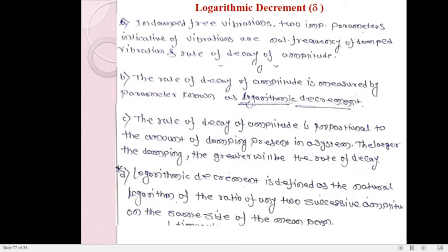In case of an overdamped system, you have seen that the systems do not perform further oscillations or vibrations. As soon as you apply the force, they get displaced from the mean position, reach the extreme position, and from there, depending upon the conditions of damping, overdamped or critically damped, they try to come back to the mean position as soon as possible, but will reach the exact mean position after a certain time, or it will take infinite time.